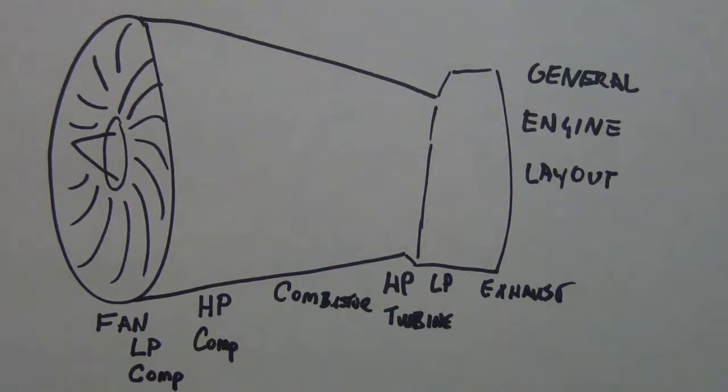Okay, that kind of gives you an idea with a fan section, fan frame, fan rotor, and stator, and then of course you have a fan shaft. Now, I mentioned the spinner cones. You have a front cone and a rear, and it's pretty much the same for the dash 5B versus the dash 5A when you compare. The difference here is just the number of stages of the low pressure compressor.